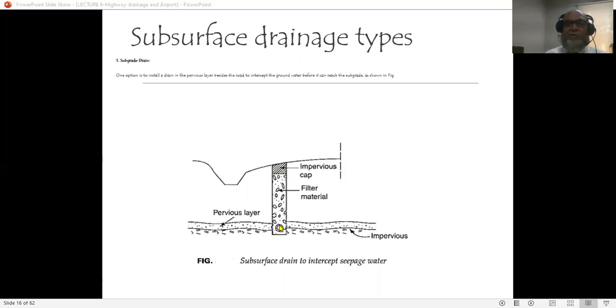It is so designed that the opening should not allow a minimum particle size of around, say, 0.075 mm to pass through it. Otherwise, if the size of perforation is larger, then the silt will also go and this can choke your system.